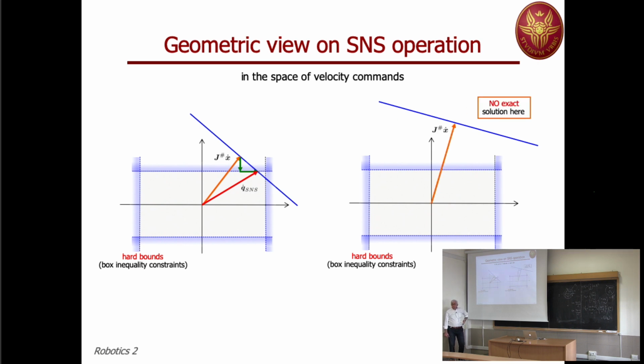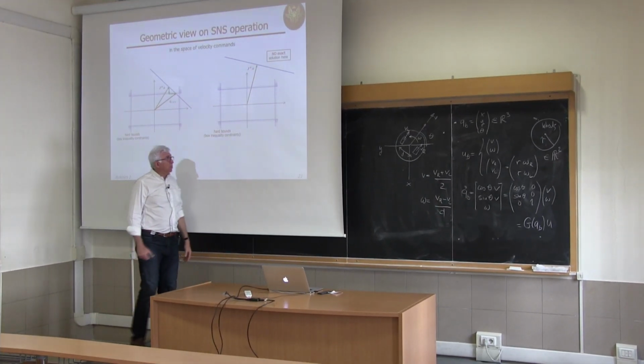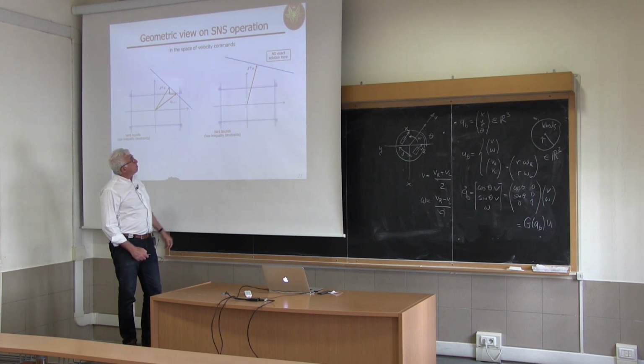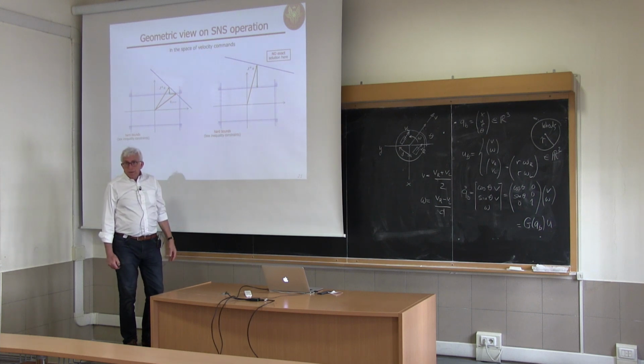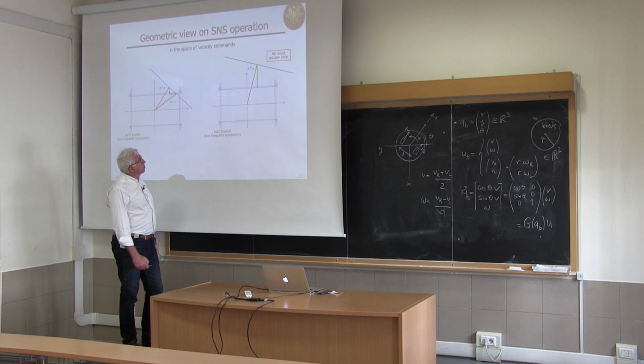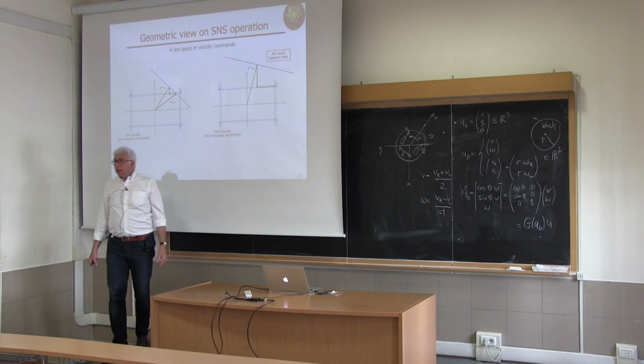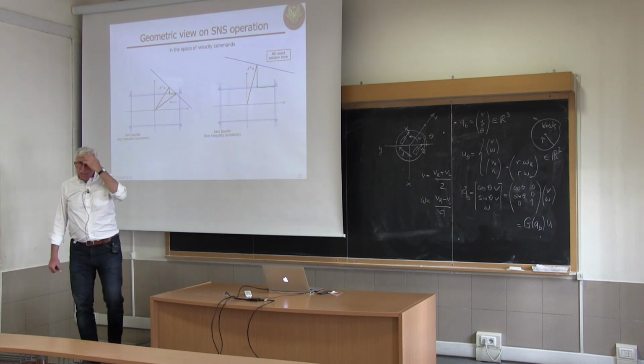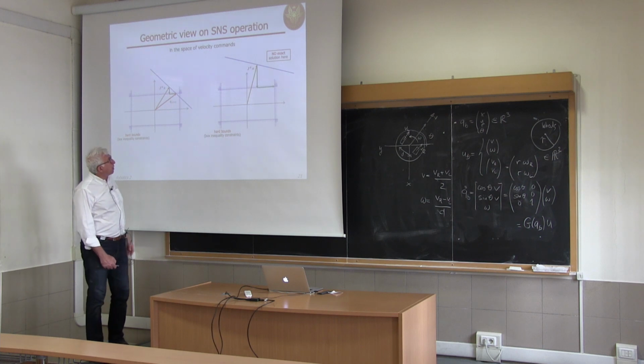So first, we will look for the minimum norm solution, so we end up with this. Again, we have Q2 dot, which is overdriven, while Q1 dot is inside the boundaries, because it's inside this vertical stripe. So we bring back Q2 dot to its saturation level, and then we adjust by reducing the error with respect to the equality constraint, also Q1 dot. So we move up to there. More than that, we cannot go because we would violate at this stage the bound on Q1 dot as well.